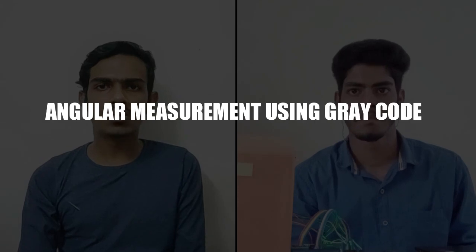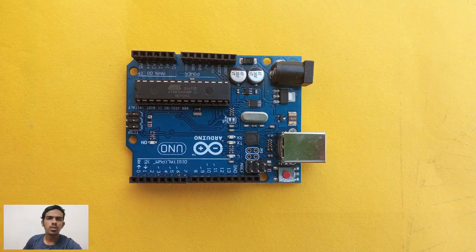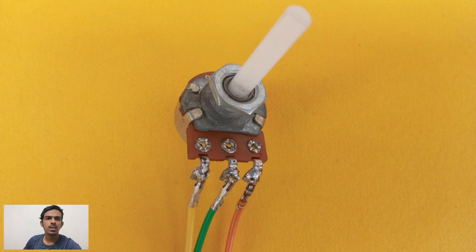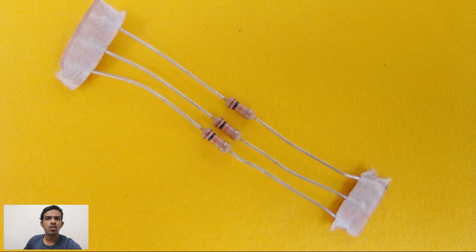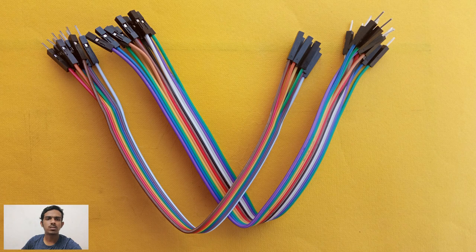The project name is Angular Measurement using Gray Code. This is a device used to measure the angle that the shaft rotated at a fixed point. The components we used for this project are Arduino Uno R3, LCD 16x2, one 250 kilo ohm potentiometer, one 220 ohm resistor, 3 photoresistors, 4 10 kilo ohm resistors, 3 green LEDs and some jumper wires.